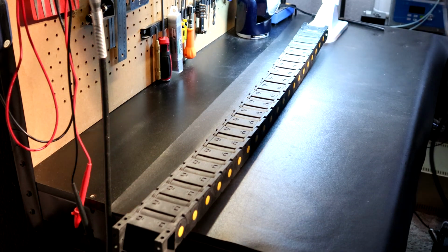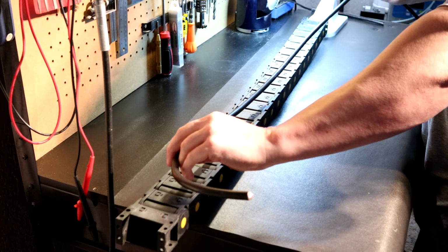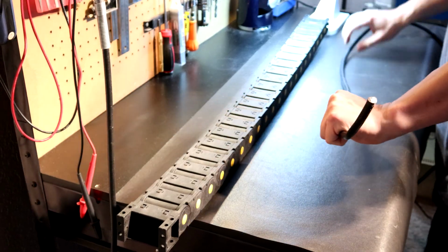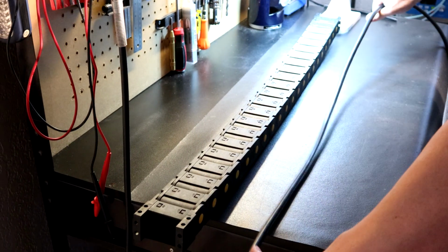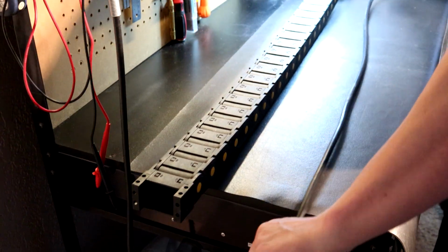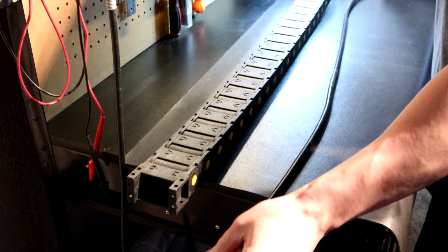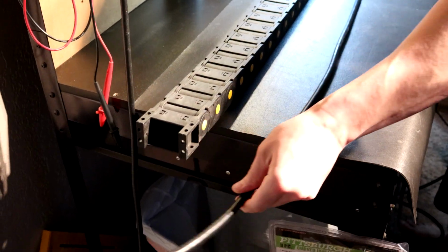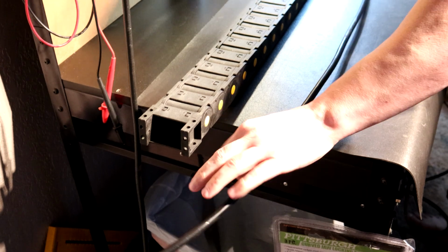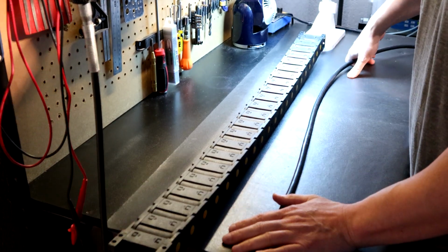A lot of guys skip this step, and what they'll do is they just insert it right into the cable chain. What you want to do is lay the actual cable out so that there's the least amount of stress on it. You can see we got some glue here on the cable because it was actually taped. But you want to lay it out straight with your terminals so that it's as straight as it can be with the least amount of stress. Once you've done that, you have two options.